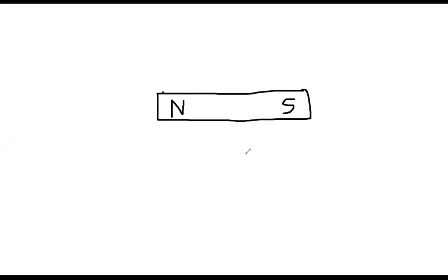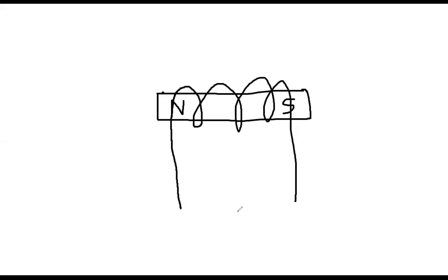It will not so easily provide you the flux. So you need some sort of winding. For example, you place some coils or winding, and then this is the DC, this is VDC, for example. You have to send some DC power. So if this is DC voltage, then DC current is going, and that DC current basically will excite this magnet. Consequently, they will originate flux.